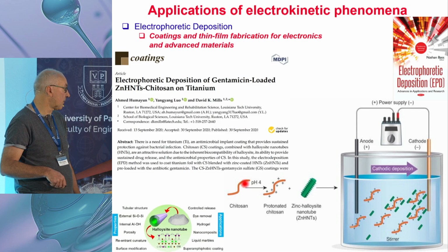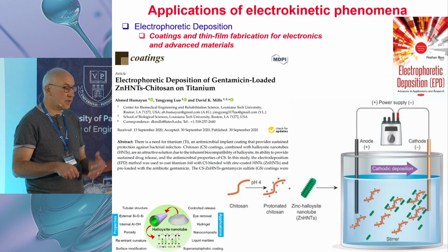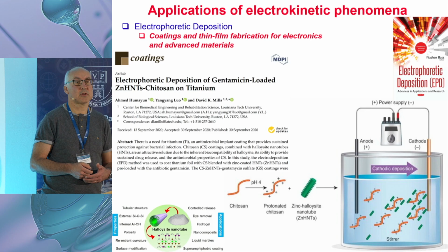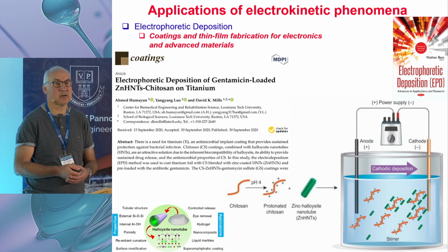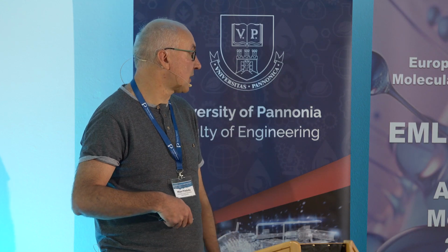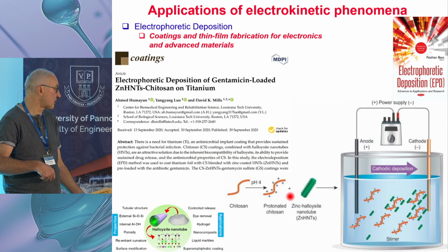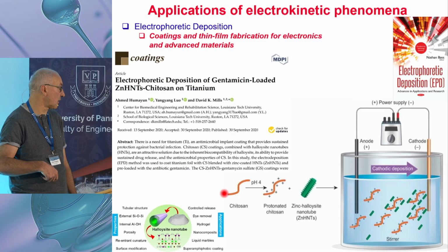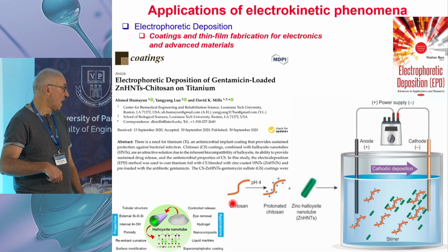And for example, in this application, it's for titanium implants. If you want to improve the healing of the implantation of the artificial joint, you can deposit on the titanium material also some basic antibiotics or some organic substance which prevents inflammation, etc. And as you already know, if you choose proper pH for this process, you will have even the biomolecule charged.